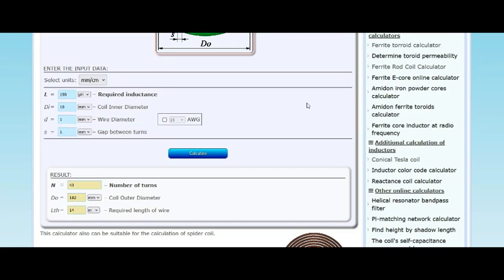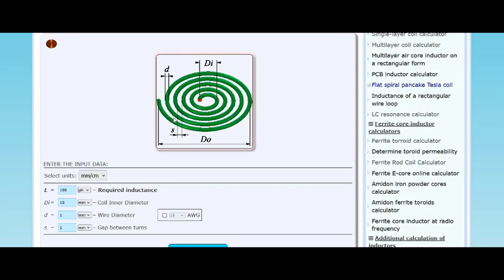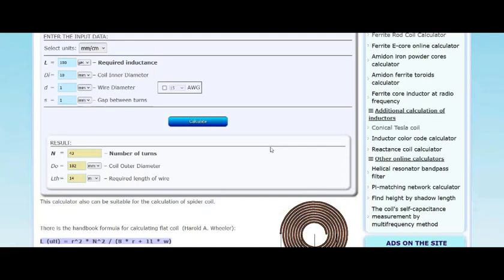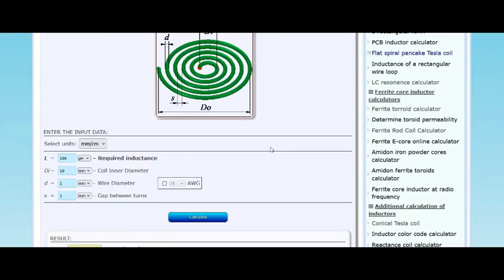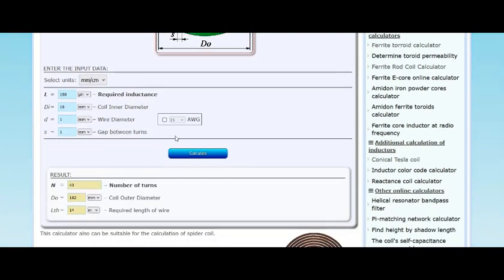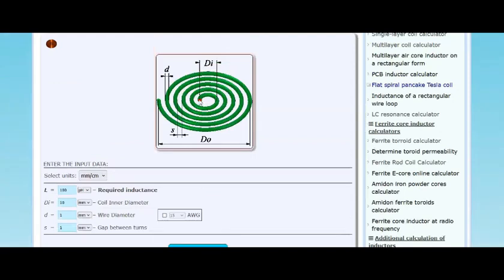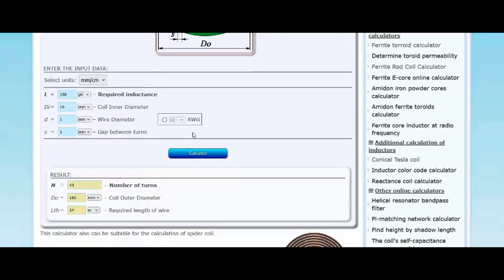And if you spaced it out where you have an extra wire length there, I believe, and this is a little bit of a guess, you could go about 4 times as fast before you would run into proximity effect, as opposed to if they were right on top of each other. Again, this thing is kind of set up backwards from how I'd like it. But another question would be, it'd be nice if you could make this air core really big here in the middle, because then you don't have to spend all your time winding.